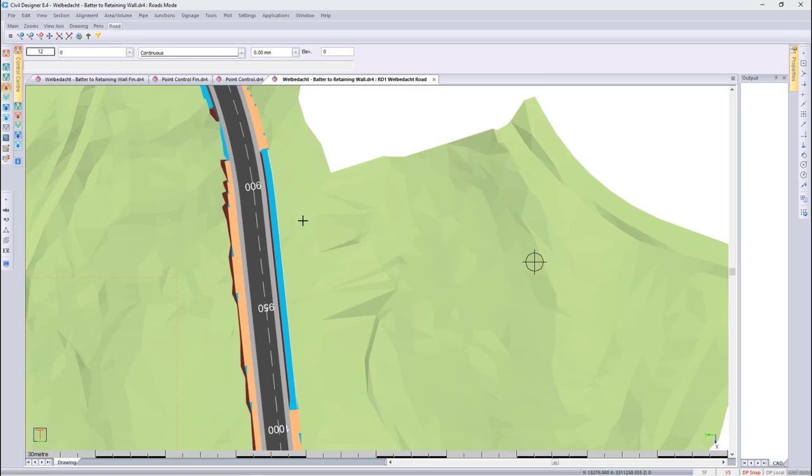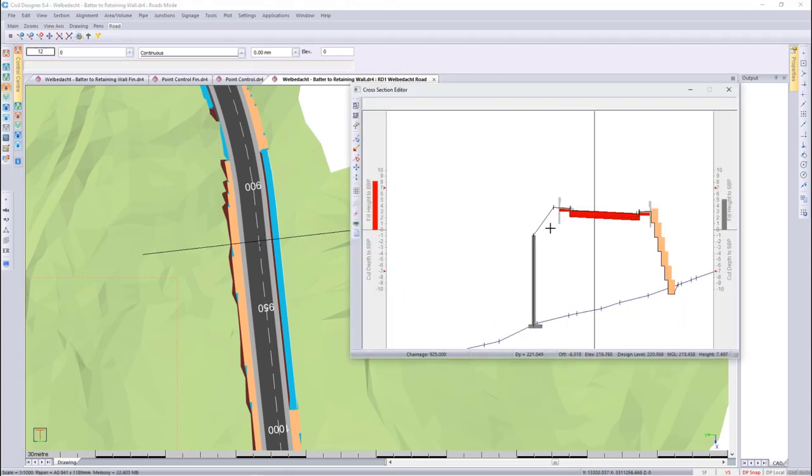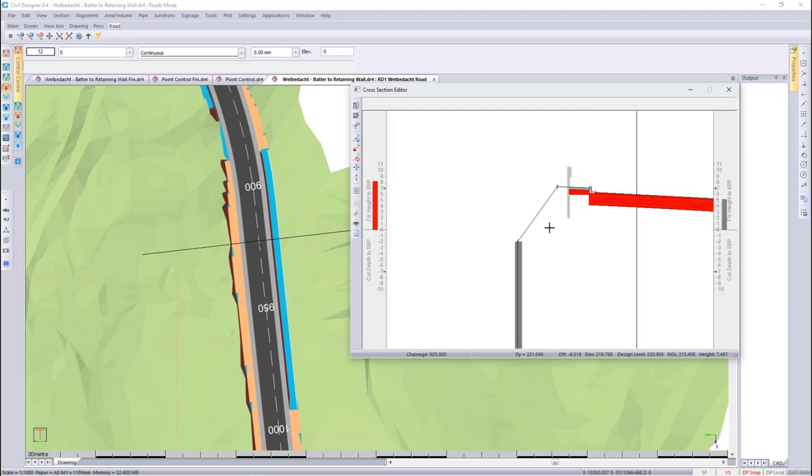Let's take a look at what it looks like in a cross-sectional format. Going to Section, Graphical Edit, specifying where you want the cross-section, and then just zooming in there. The emphasis being on the grade that we retained from the template. So if I were to go and right-click there, go and select Measure, place my cursor close to that point, go and press J, Enter, go to that point, J, Enter, and then just check that your grade and your slope is correct.